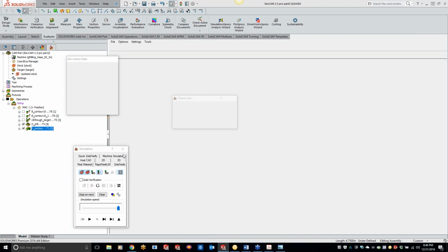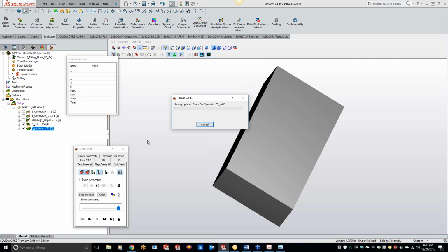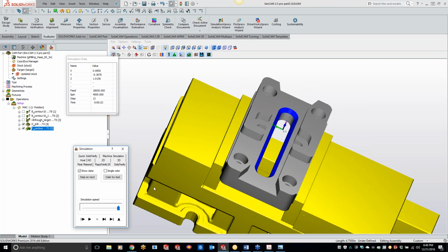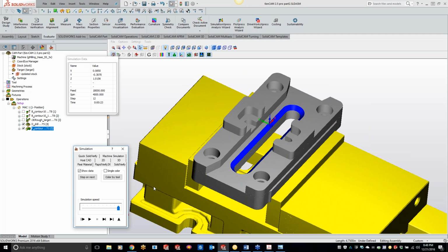You know, Kevin, there are two great things that just happened right there. The first one that I saw was being able to change tool geometry on the fly. That would be perfect if you had, let's say, a regrind or something like that. If you're pulling something from a library, that's fine, but you have full control over all of that information. And then the next thing you did was, instead of starting from the outside of the geometry, you can put your starting point wherever you want. Absolutely, and it totally applies to everything. It really goes to that level of control in SolidCAM.